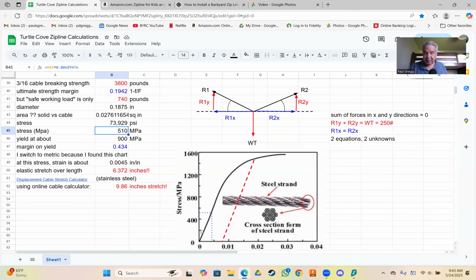If you manufacture cable, you're not going to want to get sued. And plus, cable can get damaged, a few strands break loose, it gets old, it gets stepped on, all kinds of things like that. So the reason the manufacturer says the safe working load is 740 pounds is because sometimes a person's life depends on this cable, and they're going to have an extra factor of safety in for that. You don't know how old the cable is, if it's had chemicals on it, or if it's been stepped on, or if it's been hit and has some fibers broken or whatever.